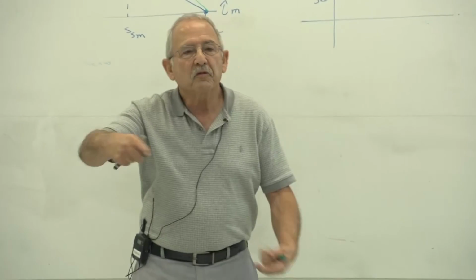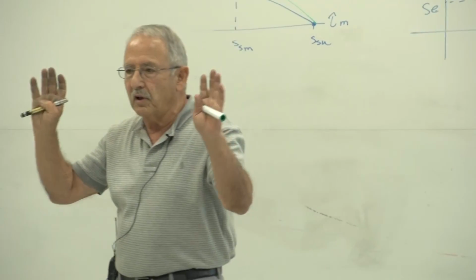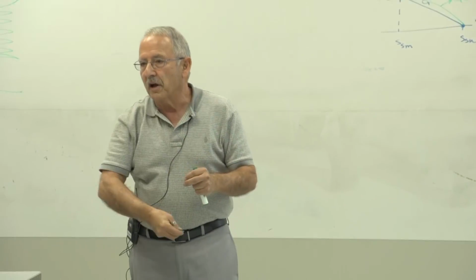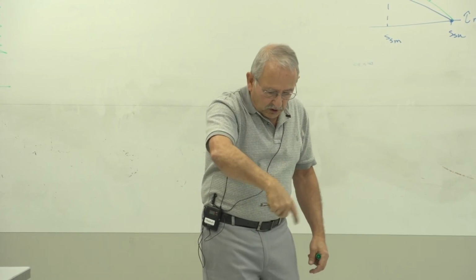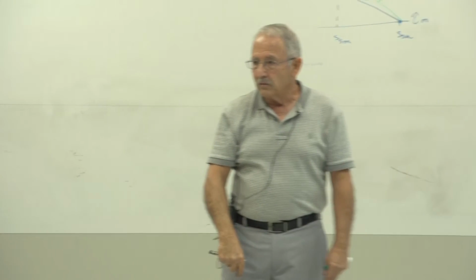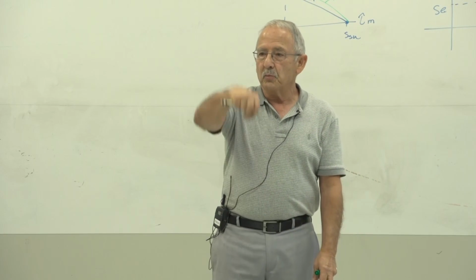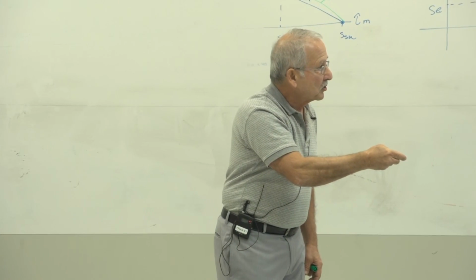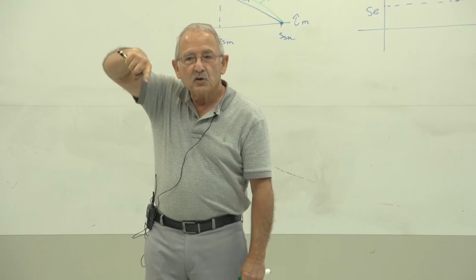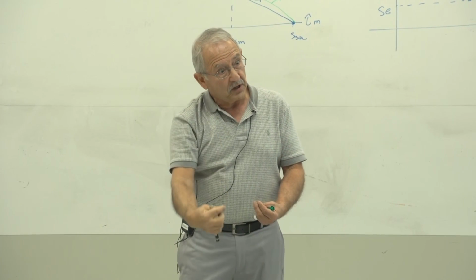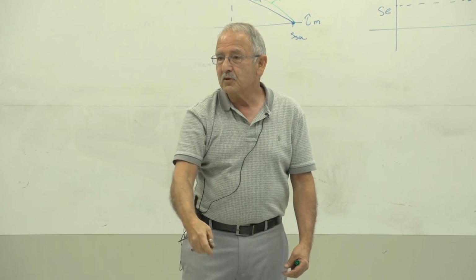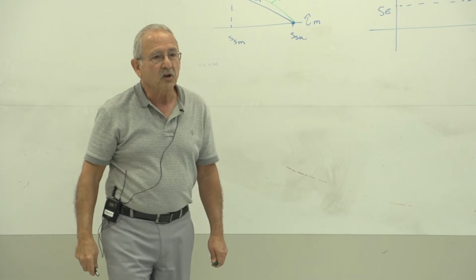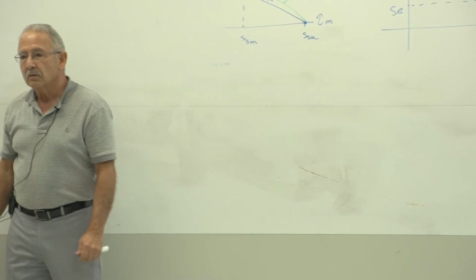You coil the, if you have a regular, run-of-the-mill garden hose, they usually have a line on them along the length of the hose. And you put this circularly, very nice and neat on the ground, and just pick up the end and pull it up. Basically, that's what you're doing. And if you do that, you see that that line that's on the hose twists, which means that that hose is in torsion.